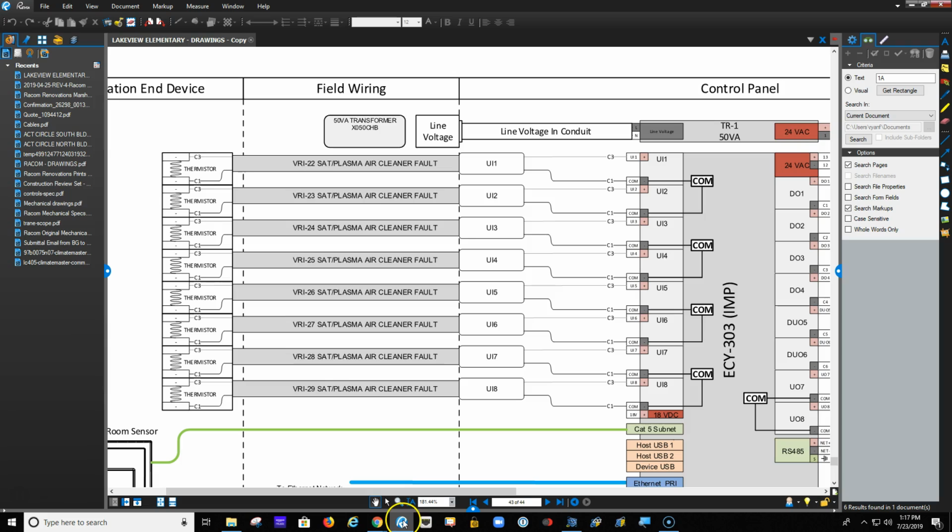Let's go back to our program. Universal input 1 is defined in the software as hardware input 101. And it's 101 because they consider this to be the first expansion module of this controller. So 100 would be first expansion. If there was a second one, like on an S1000, you would have input 101, input 201, input 301 as you went down onto each controller. All right, so 101.